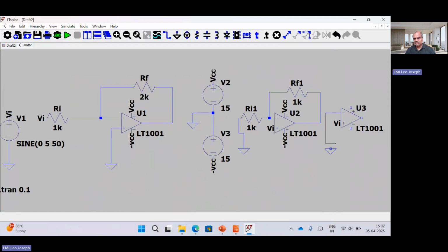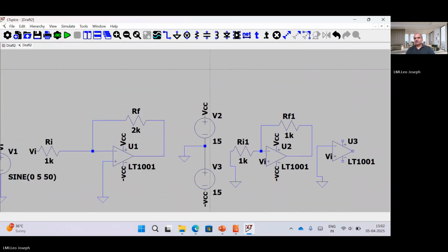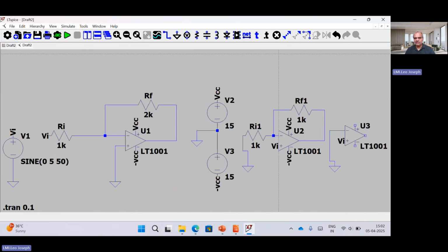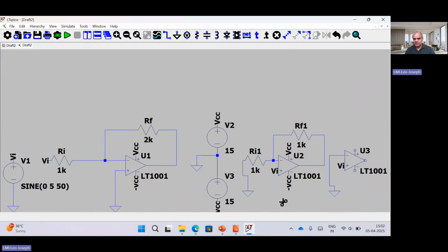See how we are building the circuit without any confusion. We are building the circuit, right? If you want to delete, simply delete this. Now, as per the wire, you can just short this. That's fine. After this, it will go beyond our control, so just click zoom to fit. Duplication is nothing but this: this VCC I am taking and giving here, and minus VCC I am taking and fixing here.